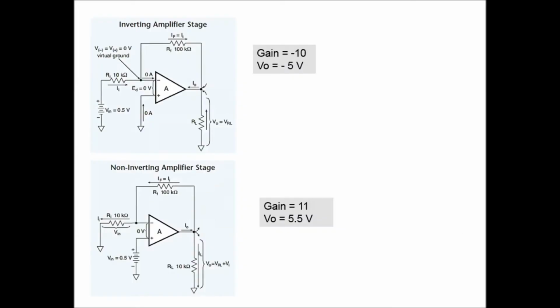For example, you can see here the current is 0, which is the first property I have mentioned just now. And the voltage at this terminal is 0 because it is directly connected to ground. So if the voltage here is 0, it means that the voltage here will also be 0. That's why V at the negative terminal and at the positive terminal is 0.